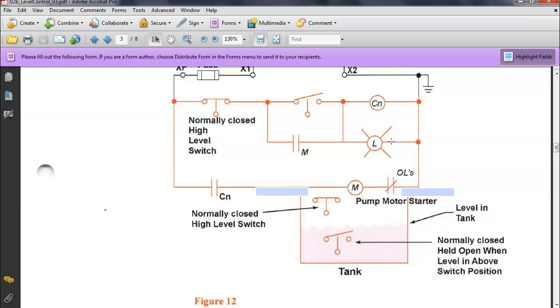By the way, normally in motor controls, these control relays, we usually call them CR, but you have to understand that's a generic name. It's going to be highly unlikely that you get out in industry and look at a print and you're going to see a relay named CR. It's going to try to give the relay a name or a mnemonic, basically what it does. So these are just generic names. All you know is that it's a symbol of a coil. So what I'm doing is I'm looking for a contact that has the same name. So this is the contact for that control relay, right? So it's just a name.